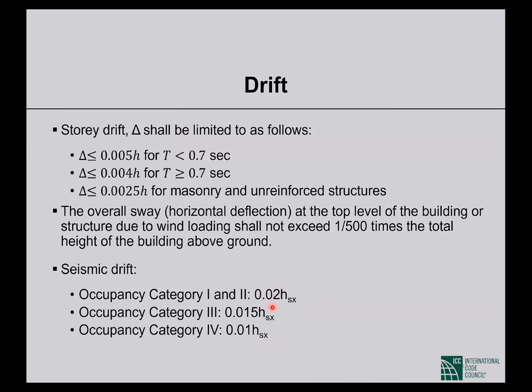We have to divide these numbers with some other number, more than one probably, in some cases, and it also depends on whether we are conducting a linear analysis or a non-linear analysis. So it depends on many other things. Please read those clauses carefully to actually be able to check these criteria.